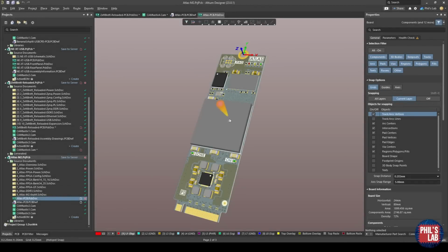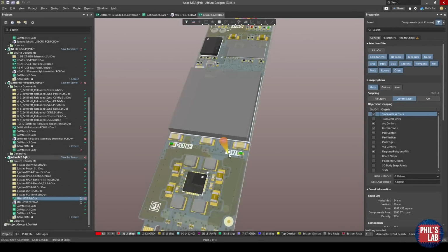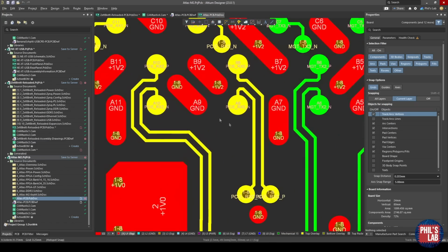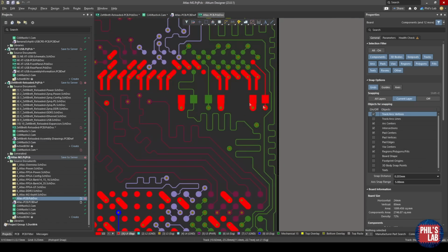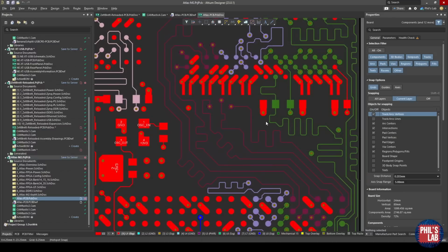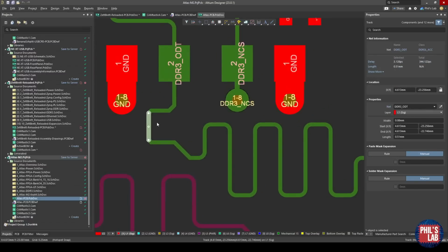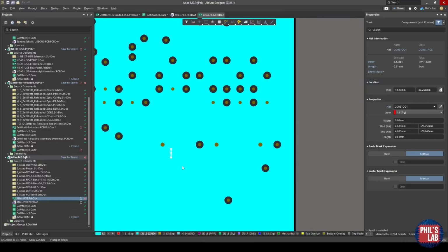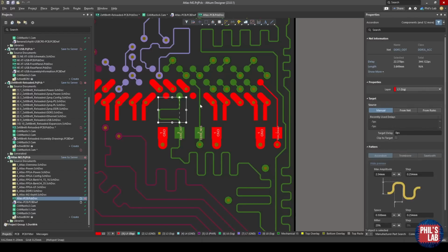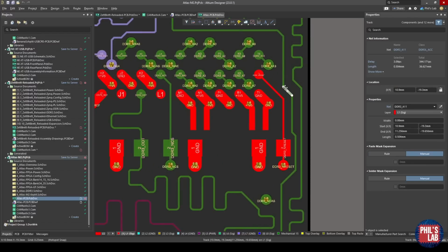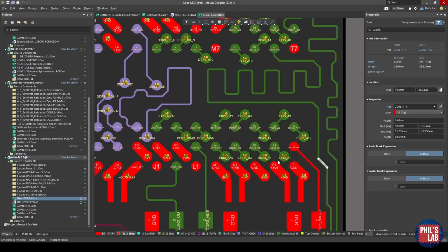Taking as an example this other board, this FPGA-based hardware accelerator, same as with the other board, I have various high-speed traces. For example, I have PCI Express, I have these DDR signal lines, and so on. And for these, I require controlled impedance traces, meaning these traces are of a certain thickness. The spacing between layer 1 and the reference plane below is a certain spacing, which is governed by the dielectric. And I have to choose certain dielectric constants to meet this controlled impedance. For example, that these lines are 50 ohms controlled impedance traces.